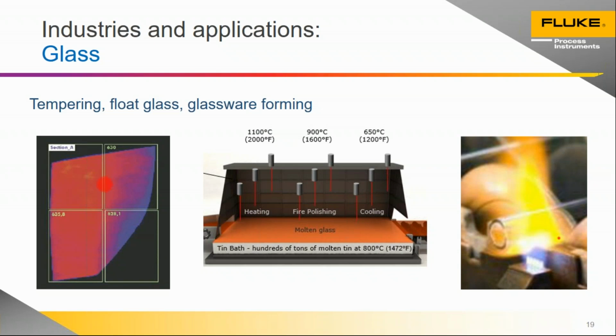But what you'll generally do is position that scanner in just a couple inches gap that you have between that tempering furnace and at the outlet of that, you'll have kind of an air quench that happens very quickly after that. And in that very thin gap between those two components, it might just be a couple of inches, you can have that line scanner look right down the middle, and as the product passes underneath, as Adam described, you have many passes of that pyrometer going across and scanning and then creating a 2D image for the user of the actual temperature profile. In this case, the customer had broken it down into 3 different zones, which is something that the software can do for you.